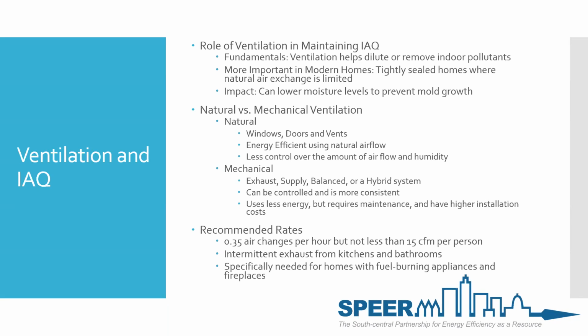You can do an air changes per hour calculation on kitchens and bathrooms to see if the rated CFM on the bath fan is pulling 0.35 air changes per hour or better, giving you that exchange of air that you need. And then specifically needed for homes with fuel burning appliances and fireplaces.